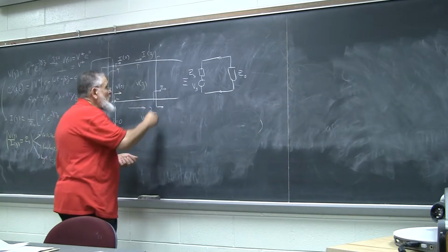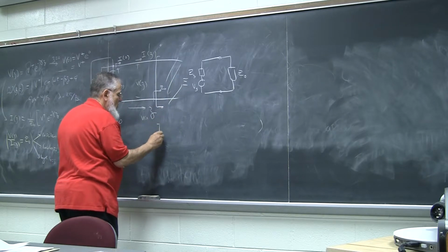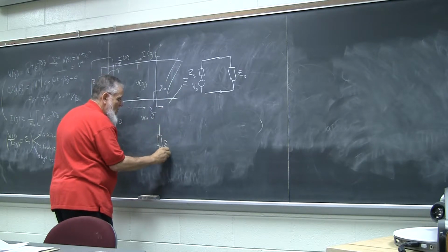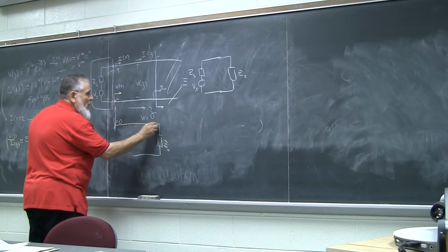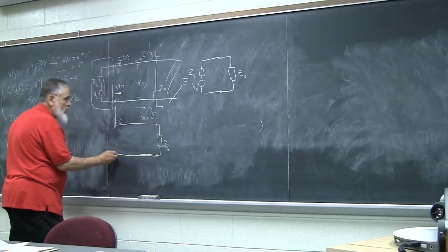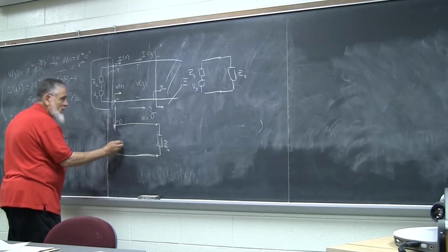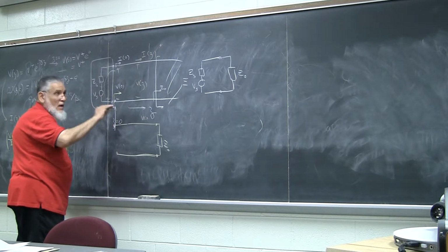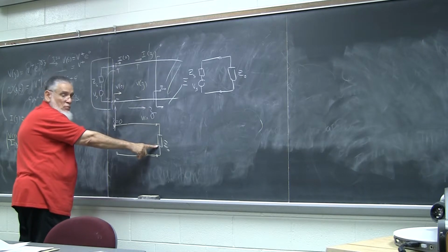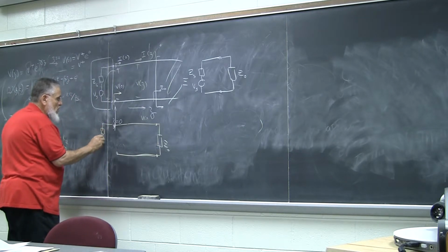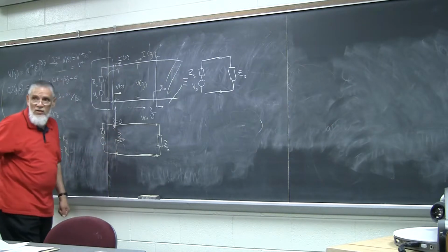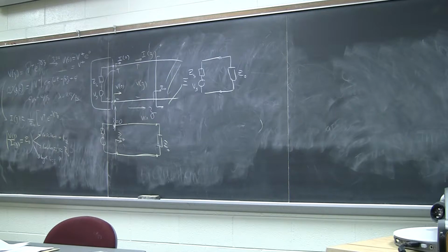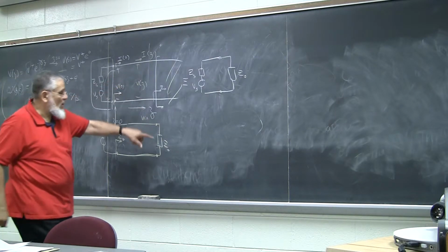So if I replace this part by Thevenin's, and here's the rest of the line, so it's a finite line now, right? That's a finite line, it's no longer infinite. I cut this part of the line and replace it by its equivalent impedance. Here's my source, and guess what? The input impedance here is still Z0. I didn't change anything. All I did is I replaced a Z0 by Z0, and replaced this part, which was Z0, by another Z0.